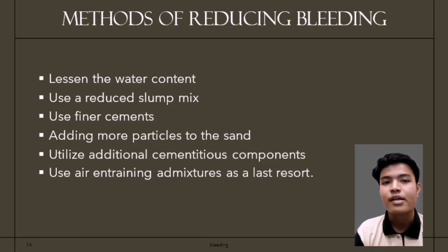Use an air-entraining admixture as a last resort. Water reducers often minimize bleeding, but depending on their chemical makeup, they could possibly result in an increase in this rate. Air-entraining admixture can also lessen bleeding by enhancing cohesiveness and reducing segregation in the fresh concrete.